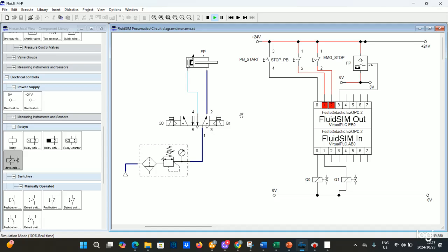Because if you don't turn this off, this and this will both be on, and in layman's terms, it's going to cause a sort of conflict, because this is going to be on, which is telling the cylinder to be in the retracted position. This is going to be on as well, forcing the cylinder to advance, right? So you have to, like, they can't both be on.